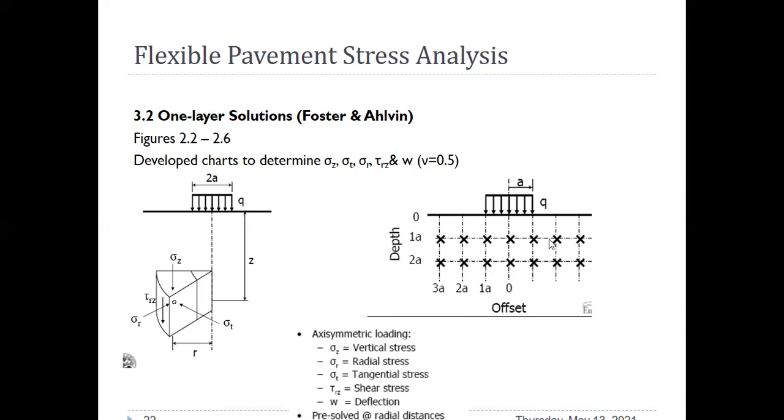So using this, we can calculate the stress at any of these points, at depth 1A, depth 2A, point 1A from the center of the load, or point 3A on the right side of the load. You can calculate on the left side at this point, or any point between here or wherever, at any depth you desire.